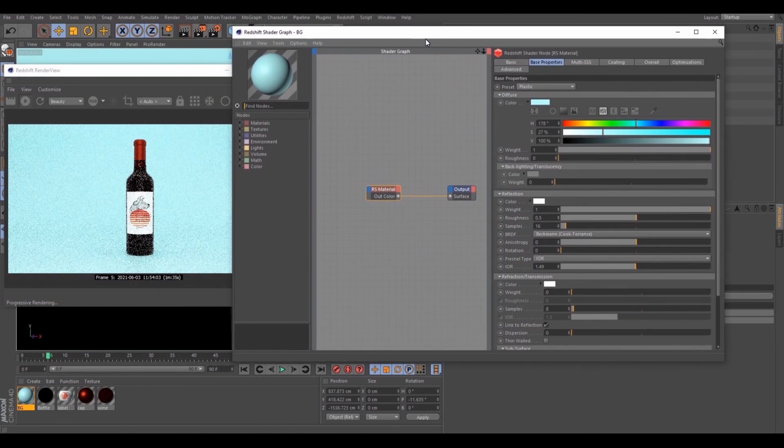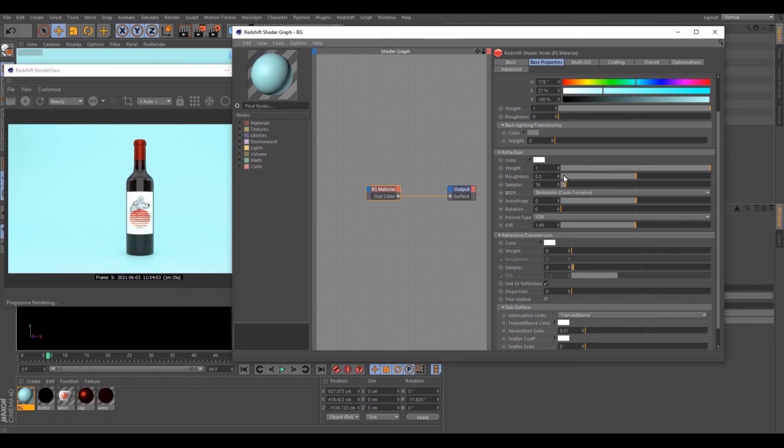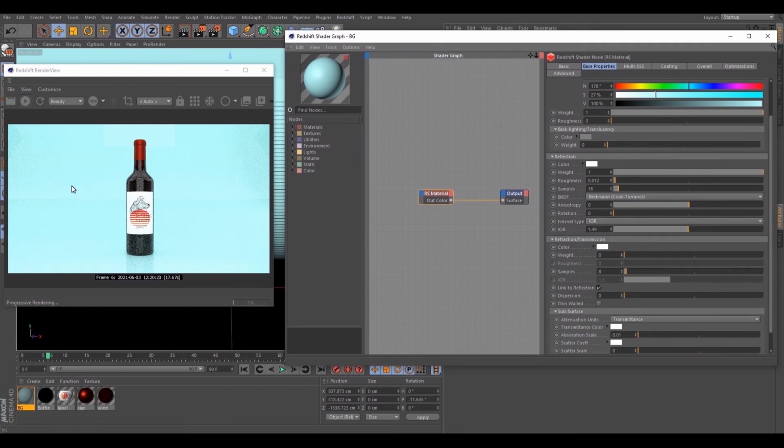I change material for the background. I change it to plastic and color make something like it was for the previous. And in reflections I made it rougher, because when it at 0 we can see all reflections. Well, I don't want them. This is as default for the plastic, and I make it something like 0.5. You can see that it became softer.